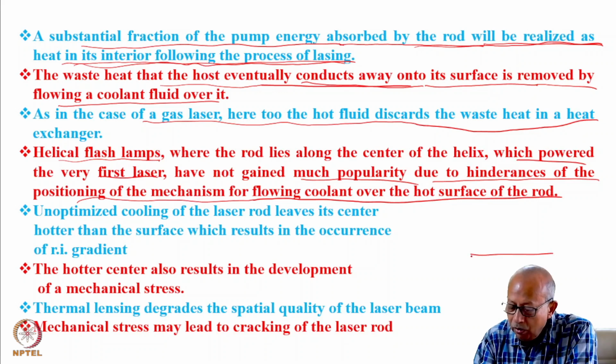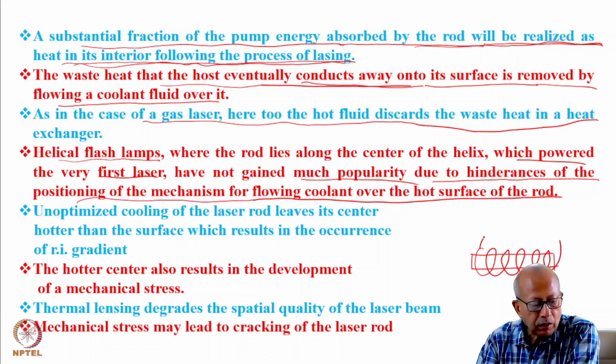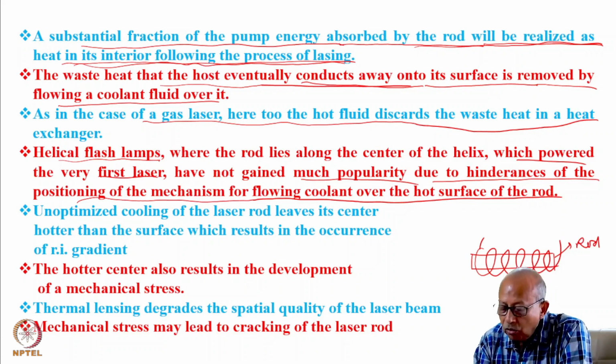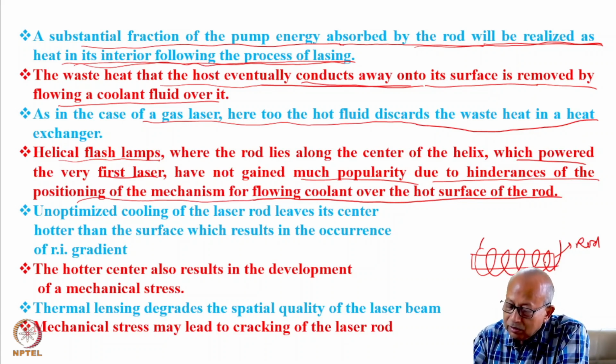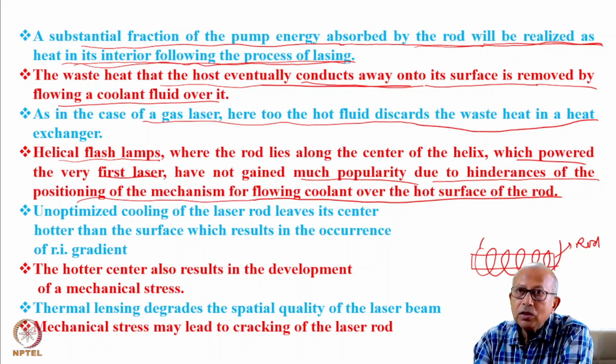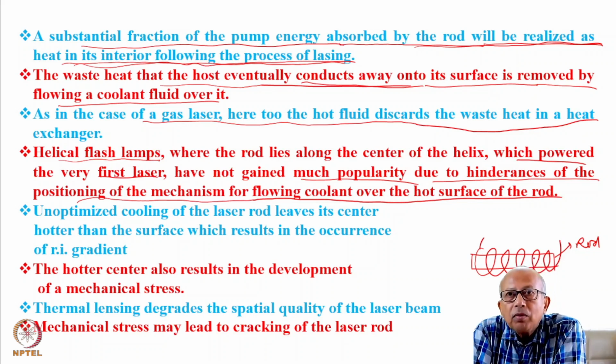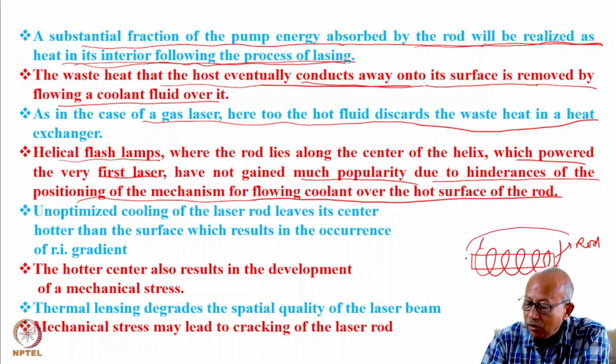See, this is your rod, and if you use a spring-shaped, that is a helical flash lamp, and then place the rod, this is the laser rod, at the center of the helix, then it will be difficult to place the jacket around this rod because of the presence of this spring-shaped flash lamp. And that is why this has not gained much popularity.